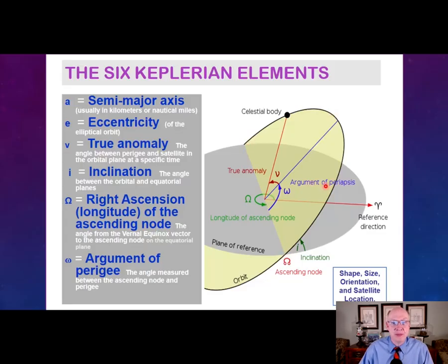And the argument of the periapsis tells us that this is the perigee point, when it is closest to the Earth. This angle right here, called the argument of the perigee, just tells us where this is located with respect to the ascending node. So again, if this was 0 degrees, that would mean that the perigee point also coincides with the ascending node. In this case, it looks to be almost 90 degrees: the argument of periapsis, the perigee right here, is about 90 degrees away from the ascending node. So that tells you how that orbit is oriented.